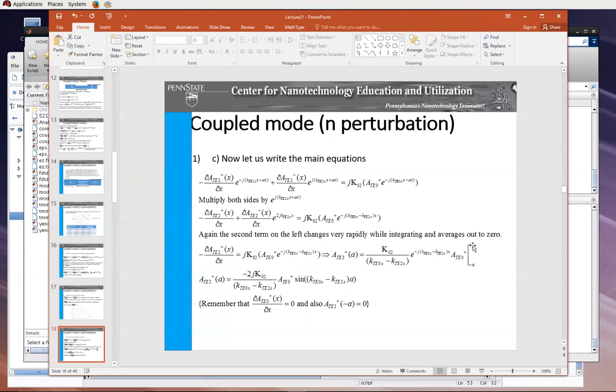If we look at the boundaries from minus a to plus a, we didn't have any second order mode initially at the minus a point. So if you put that into your equation too, you immediately arrive at the TE2 mode at point a, and that's going to be given as this. For any x value, you just replace a with x there.